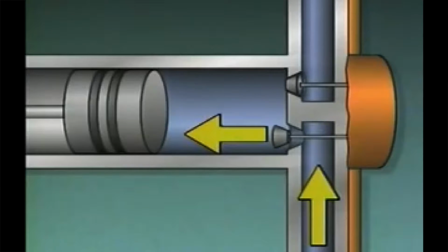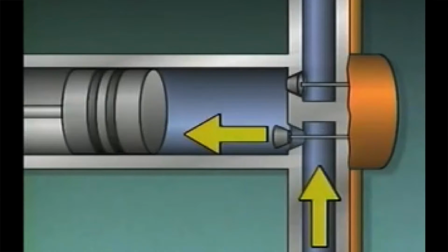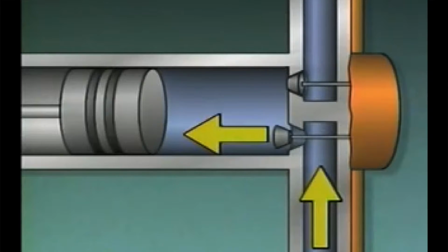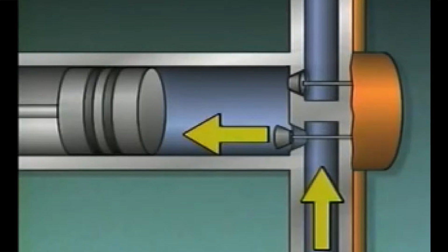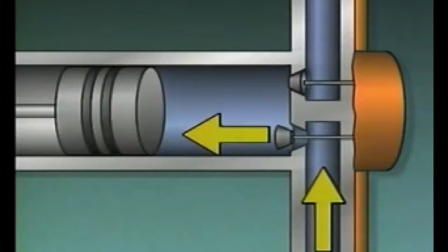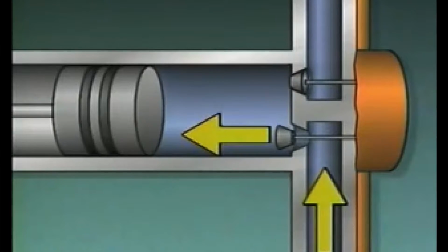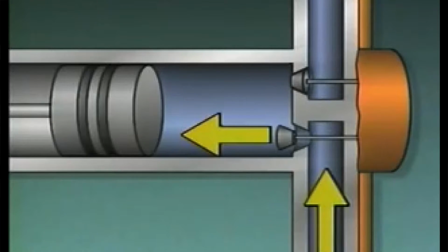When the piston is moved backwards, both valves move towards it. The suction valve opens and the discharge valve closes. Why does this happen? Well, the piston moving backwards increases the volume in the cylinder, thus creating a low pressure pocket inside, and pressure moves from high to low. So the pressure from the inlet, or the fluid in the inlet, is forced to the lower pressure system inside of the cylinder. So energy is introduced into a positive displacement pump through the changing of volumes.